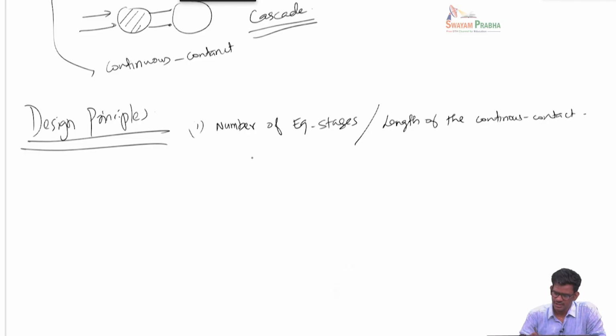To do this, we need to apply a material balance, or mass balance, and we also need the equilibrium behavior, or the equilibrium curve. We are going to discuss the equilibrium curve in more detail. You can roughly think of the equilibrium curve as one which limits the extent of mass separation.